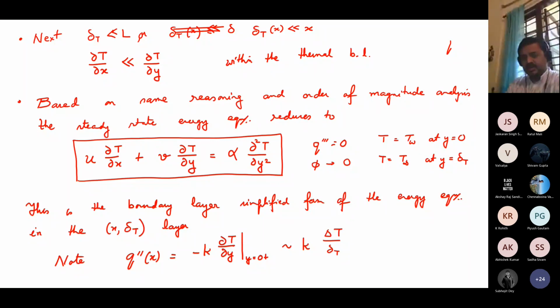Okay, that's one. Second, just look at the last expression. Higher is the slope of the temperature at y equal to 0 on the fluid side, 0 plus, higher is the rate of heat transfer. If you look from a more practical point of view, at the scaling term that I've written at the end, what does it mean?